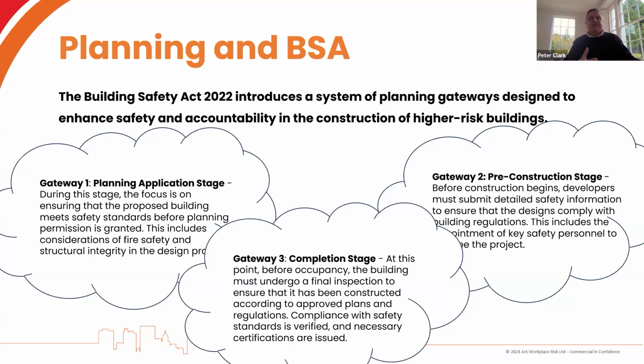someone said quite logically, well, look, if these experts have given you these documents, shouldn't you just be trusting the experts? And I think to a degree you should be, but that verification piece at Gateway 3 is crucial, because one of the examples I gave was of a sprinkler system in a building. So what we're looking for at this stage is that the sprinkler system is suitable and sufficient for the type of building, that it's been installed correctly in the right areas, and that it's been commissioned and is working as designed.